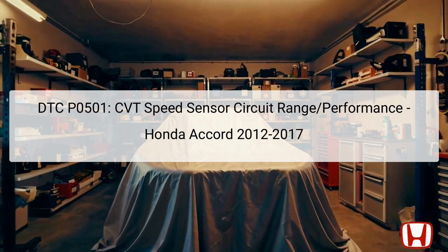This sensor, located on the outside of the torque converter housing, detects the revolutions of the secondary driven gear and transmits a pulsing signal to the Powertrain Control Module, PCM. The PCM then processes this signal to determine the vehicle's speed. If the secondary driven gear rotates and no signals are detected, the PCM considers it a malfunction. This can result from several factors, including an open circuit, intermittent connections, or short circuits affecting signal integrity.